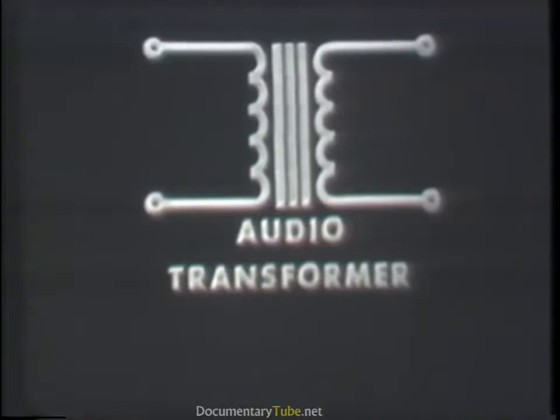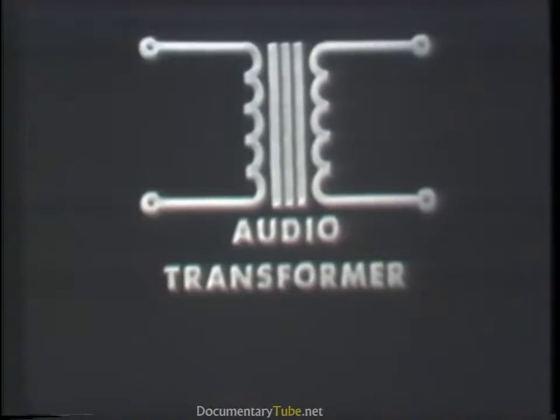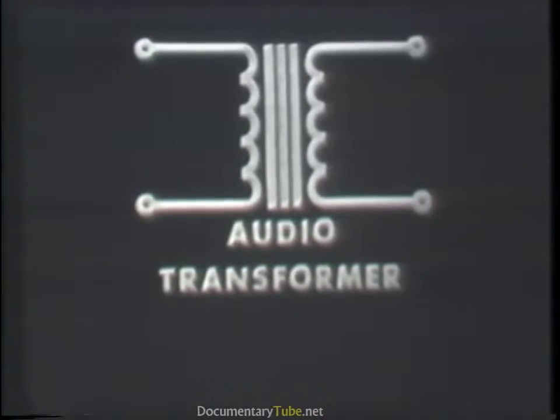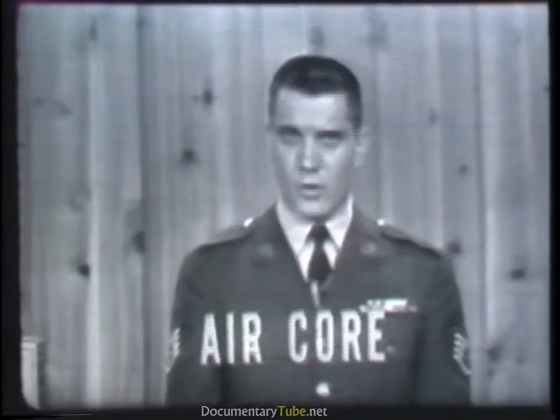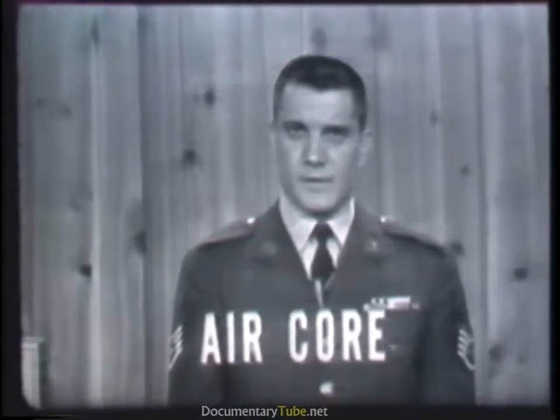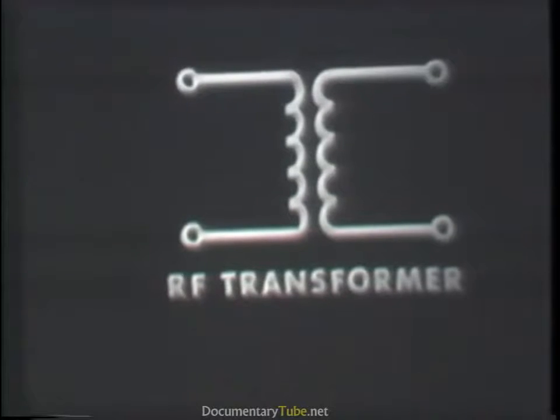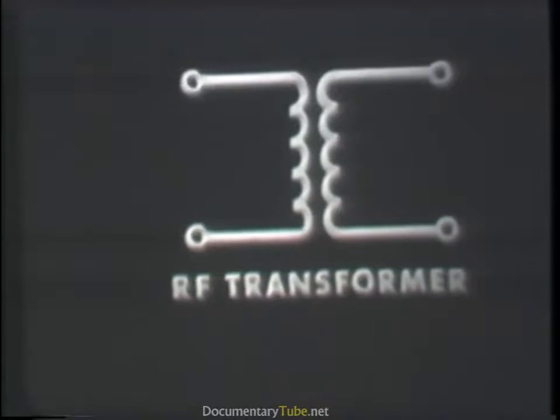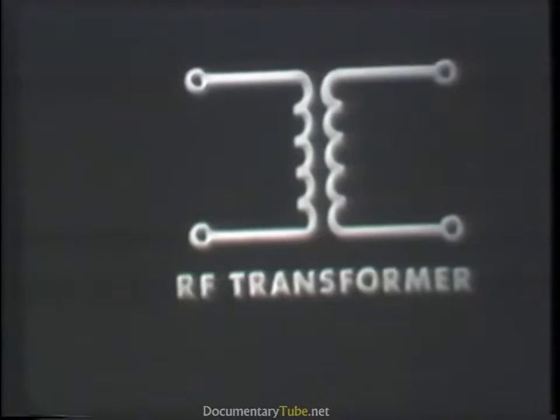Now, like the power transformer, the audio transformer, too, is usually constructed with an iron core. Well, at frequencies above 20,000 cycles per second, the RF transformer comes into use. At these frequencies, hysteresis and eddy current losses in an iron core become so great they have to be prevented. Therefore, RF transformers generally have an air core. The schematic symbol for an RF transformer, then, is easily identified by there being no vertical lines between the primary and the secondary coils.